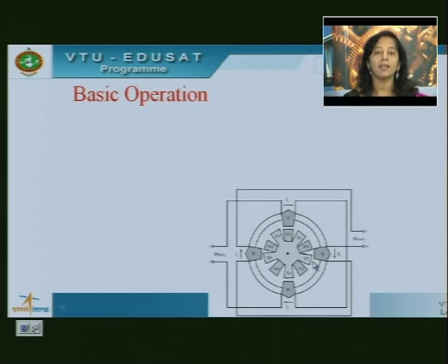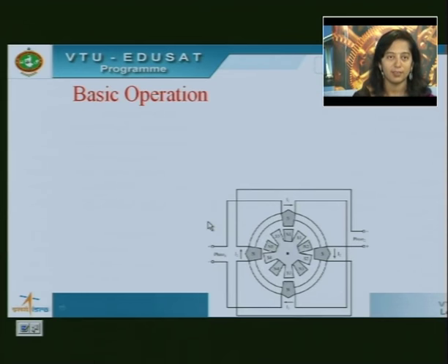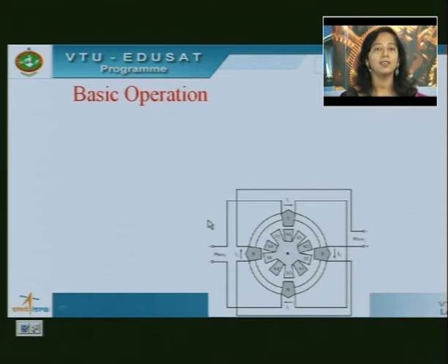So this permanent magnet stepper motor has the rotating shaft in the center using a permanent magnet, and the stator poles will be temporary magnets. In the sense, how do we make temporary magnets? We are going to use windings. We are going to use copper coils wound around the stator poles.